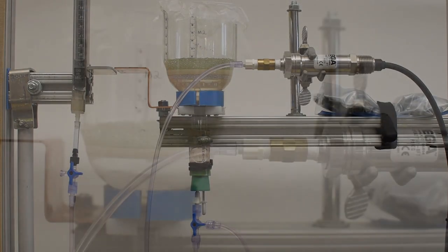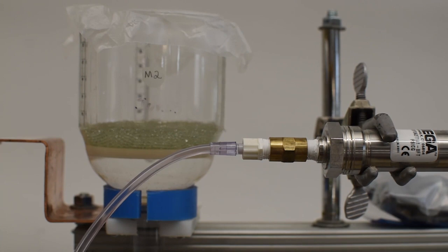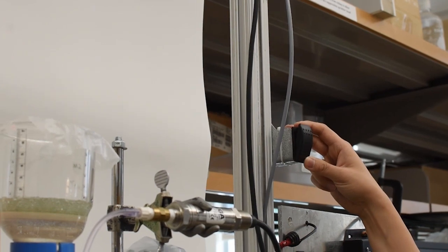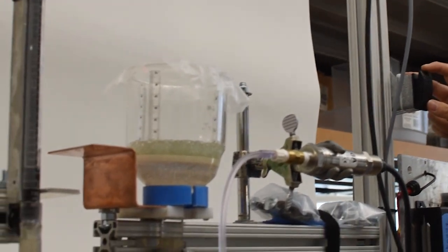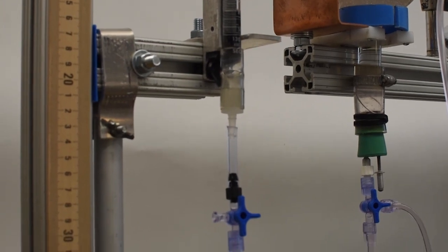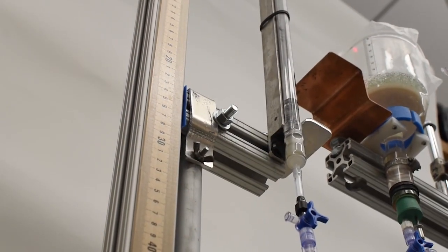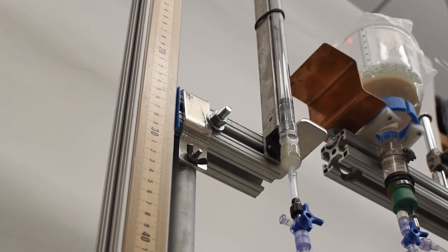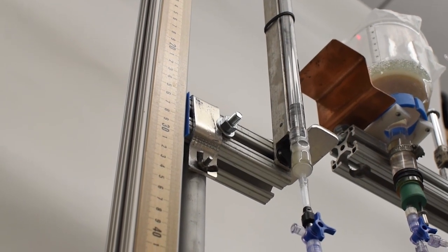The pressure transducer is located at the same height as the surface of the ceramic plate, and it monitors the matric potential of the sample base. The burette attached to another linear actuator induces a matric potential gradient by adjusting the burette reference level. It also collects excess water from the sample as the drying and wetting processes progress.